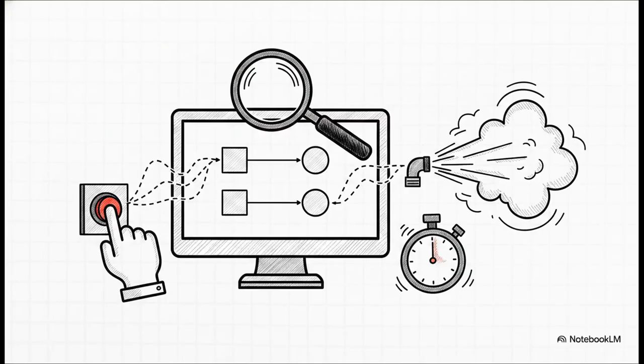Okay, we've built an incredibly sound logical structure, but we never just assume code works on the first try, right? Let's prove it. To test our setup, we load our project tags into the simulation table within TIA Portal and turn on the monitoring function. As we manually toggle the unlock button input on and off, we can literally watch the sequence of M bits cascade exactly as planned. We watch M0.0 hand off to M0.1 all the way down the line, verifying our logic is holding strong. Most importantly, we're verifying that only upon the transition to M0.6 does the TP timer actually start.